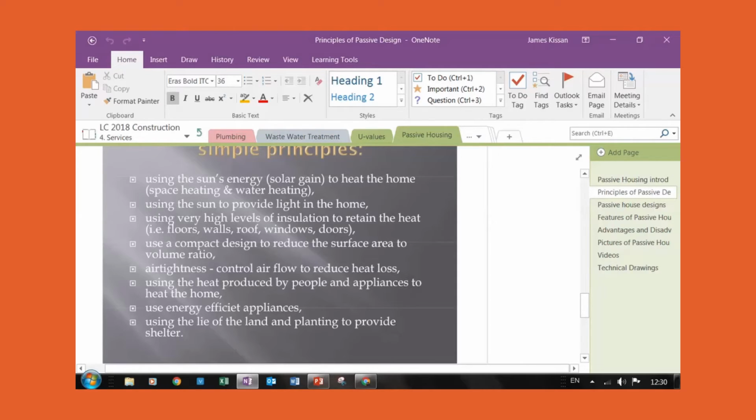So, for example, some people might be living in a traditional bungalow. The problem with the traditional bungalow is you have a long hallway with bedrooms either side, and even in the middle of the summertime, that hallway is still dark. The reason it's dark is there is no window, there's no natural daylight getting into the hallway. So in all these designs here, a lot of these houses are open plan, and we try and minimize the amount of hallways, because if we have hallways, we are going to have dark spaces.